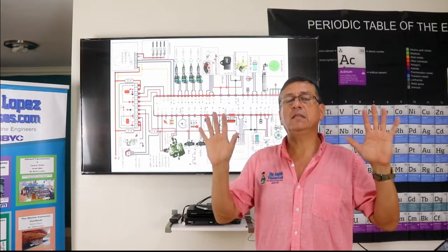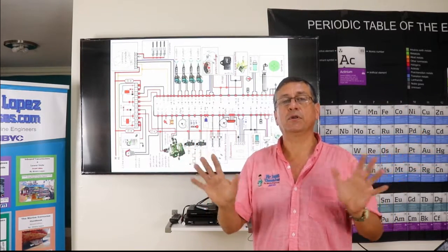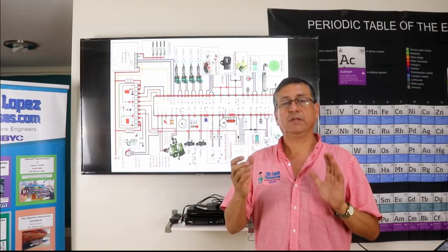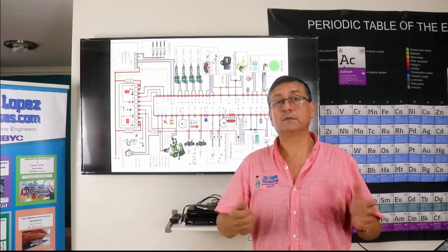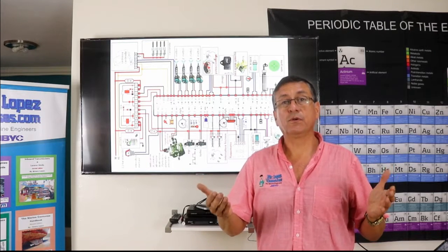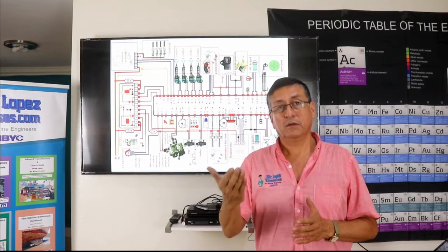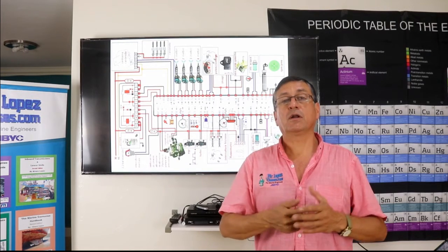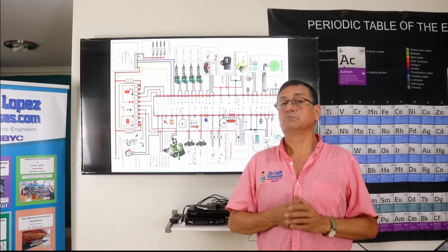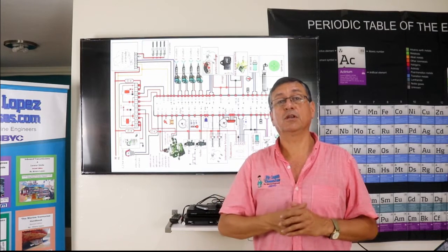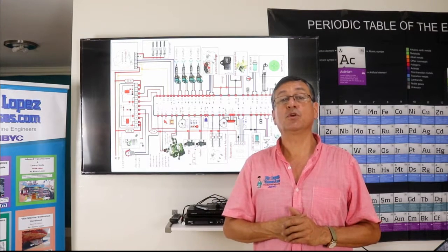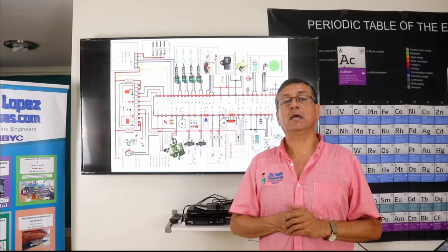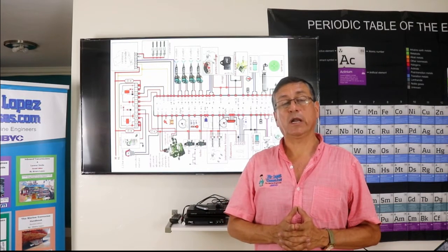Those are 99% of the sources of problems. Once again: the air filter, pressure on the fuel transfer pump, low pressure pump, power on the fuel injection pump, power on the computer or on the solenoid shut-off valve, and pressure on the common rail.